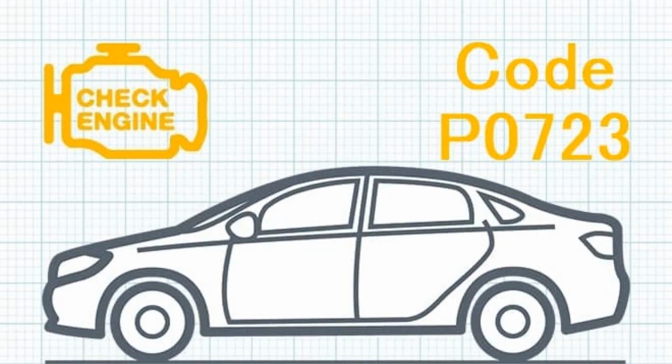Fault code P0723 sounds like output shaft speed sensor circuit intermittent erratic. Often, in OBD2 scanner software, the name may have the English spelling, output shaft speed, OSS, sensor circuit intermittent erratic. Technical description and decoding of error P0723. Diagnostic fault code P0723 indicates an intermittent output shaft speed, OSS, sensor signal.